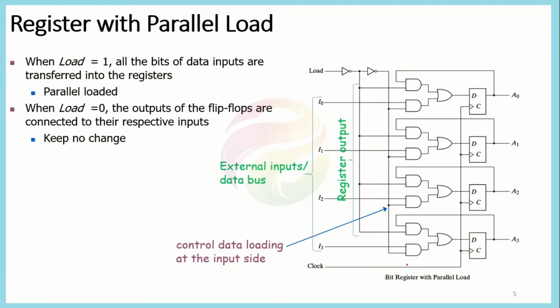Generally, anything or combinational circuit that is attached to the clock signal is not recommended because of various speed and other issues that are related to the clock signal. So we should have a certain kind of extra circuitry involved in the system so that we can handle these kinds of constraints. For solving this constraint, we design a 4-bit register with parallel load.